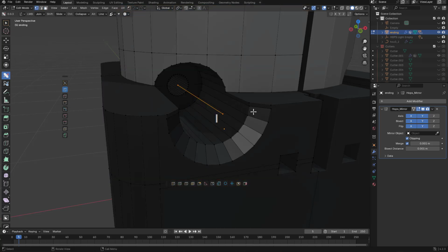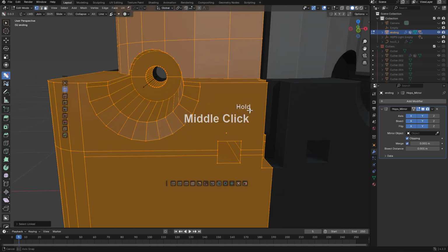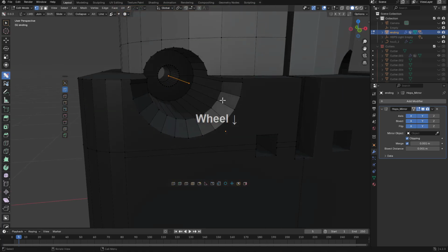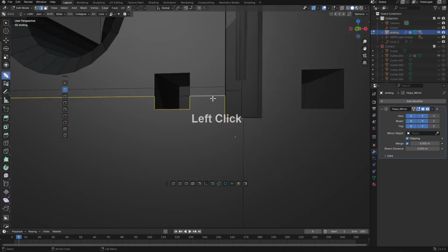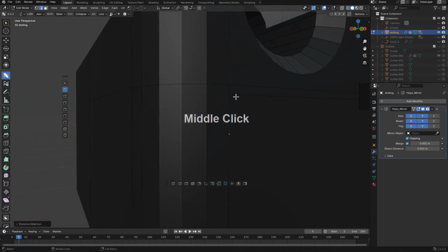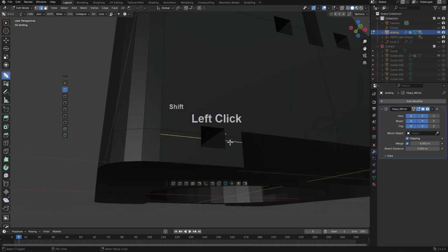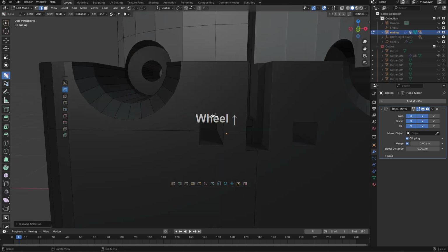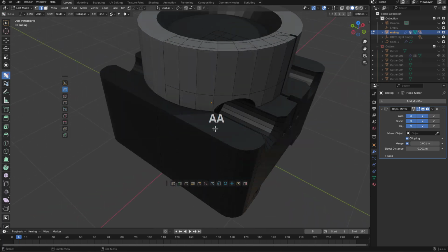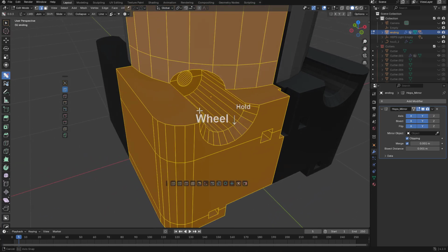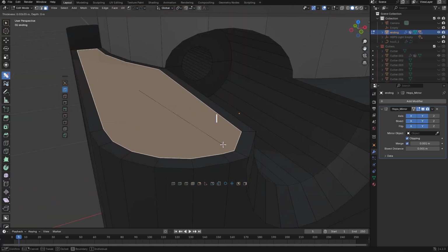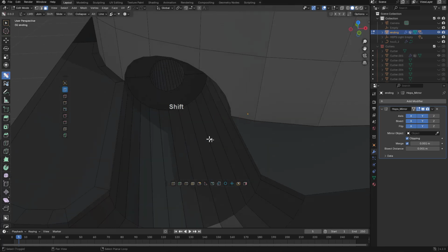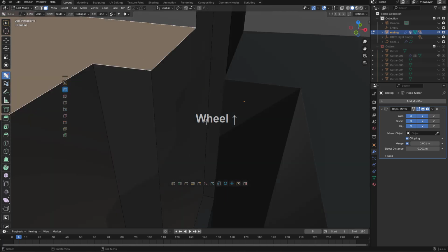So I'm going to select this mesh with L and press Control-I, and we can get rid of those little strays that were happening from whenever we converted this into a spin object. Alright, and just looking at this, analyzing what we're needing to do in order to convert this into a subdivision object. For this, we'll press I, we'll press B in order to keep the boundary loop. Just kind of setting the stage here.